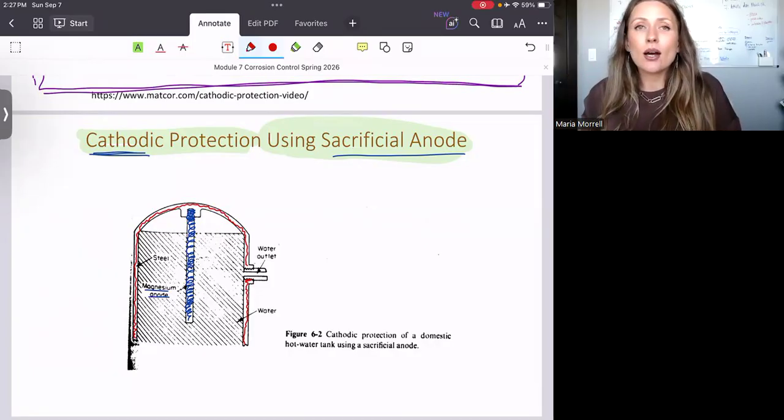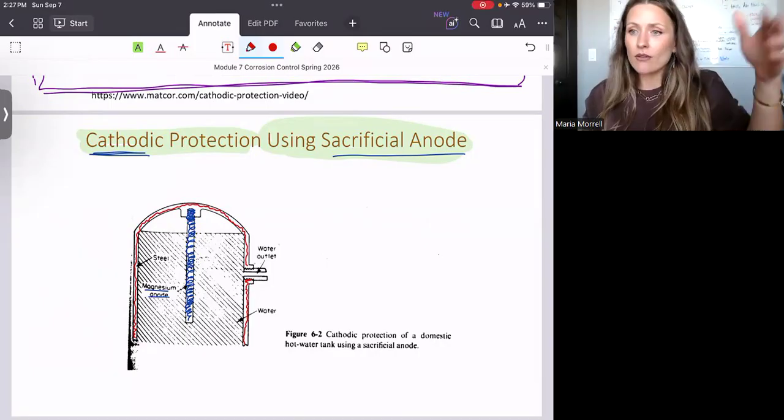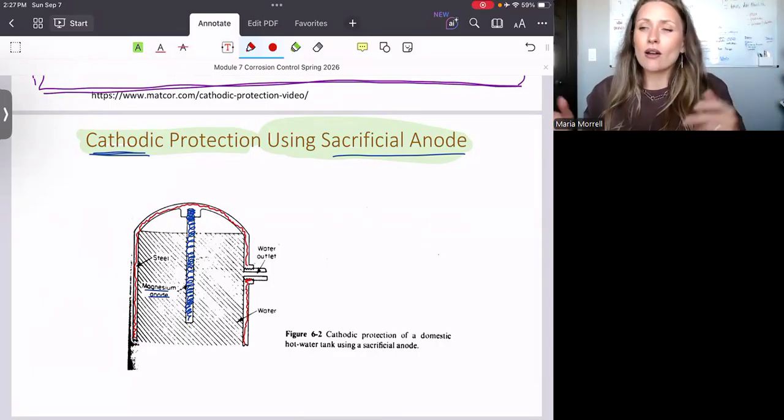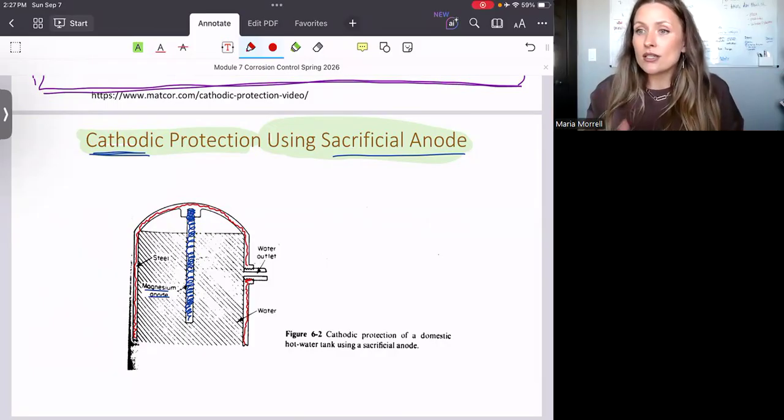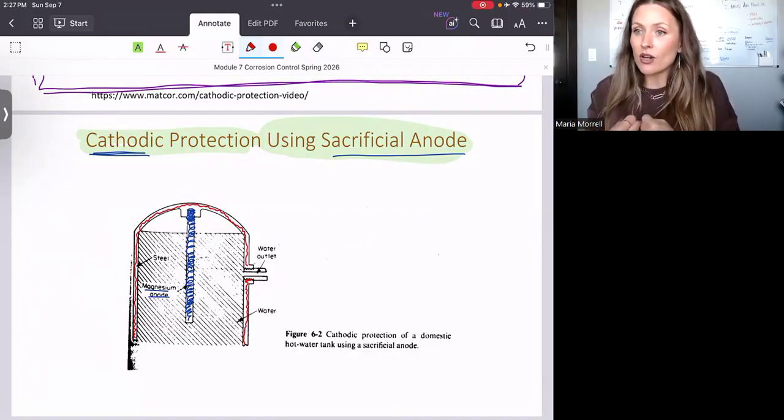If you plan to travel on a boat, or if you have a boat that you store in water, it's standing in water. Depending on what your boat is made of, but let's say it's made out of some kind of steel, I'm going to take a chunk of either aluminum or magnesium. Both of those will work. And I'm going to stick it to the bottom of my boat. And that bar will intentionally, preferentially corrode while protecting the rest of my boat, right?